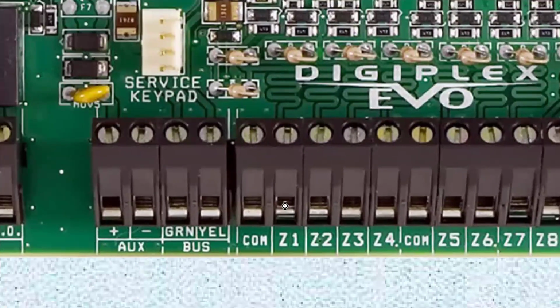And hey, all right. So this is the power that comes out of this board to supply active devices with power. Active devices such as motion sensors, glass break sensors, keypads, sometimes even maybe expansion boards or other peripherals. Now, this is not an endless source of power. You gotta read the specifications of whatever equipment you have at hand to see what's the capability, what's the voltage, what's the amperage or ampacity of this power supply.